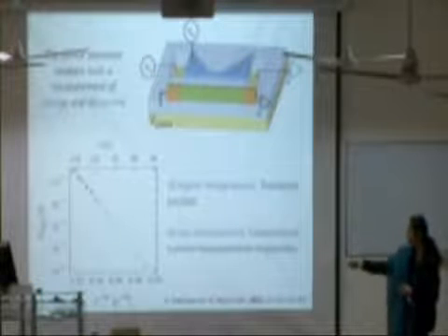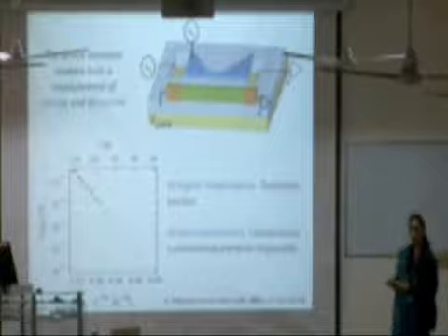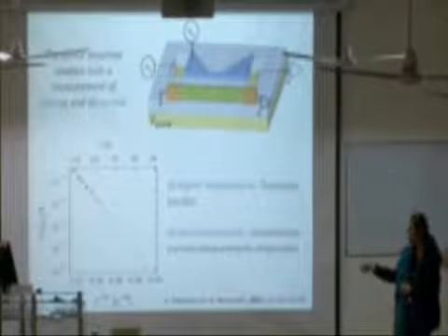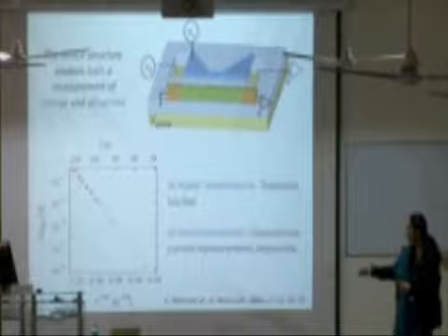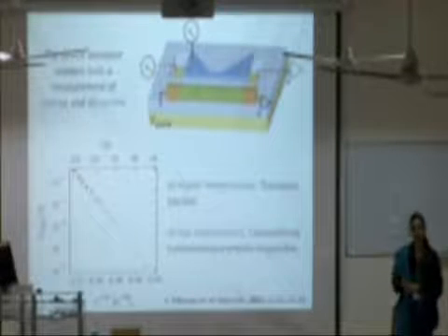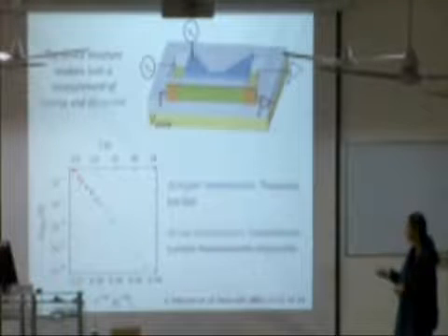So I've plotted the conductance as a function of T to the 1/4 because the mechanism of transport in amorphous germanium is variable range hopping, and the temperature dependence is T to the 1/4. So what we've seen here is that we were able to measure resistances as high as 10 to the 19 ohms by just applying 1 volt across the material.